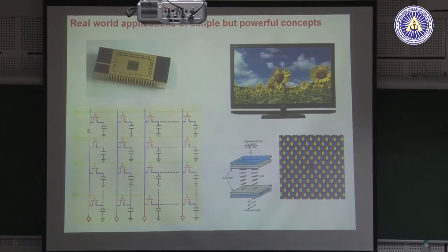And then when you make a DRAM cell, this transistor acts as a resistor here. So it's basically an RC circuit. And how often do you have to recharge your DRAM? How often do you have to refresh your DRAM? How do you get the time at which you need to refresh your DRAM? That comes from a simple RC circuit analysis.